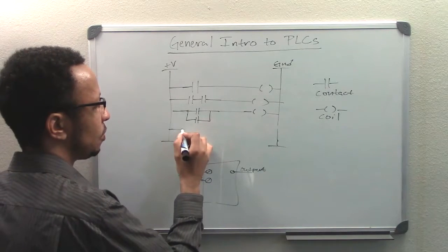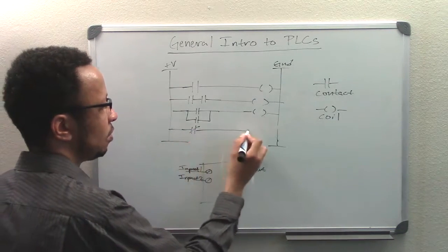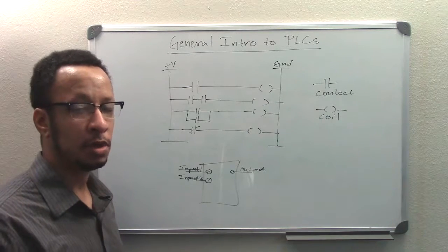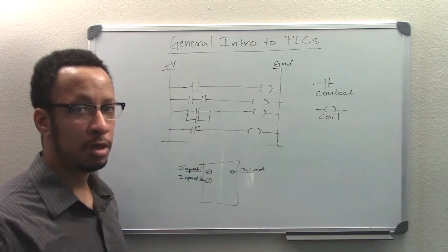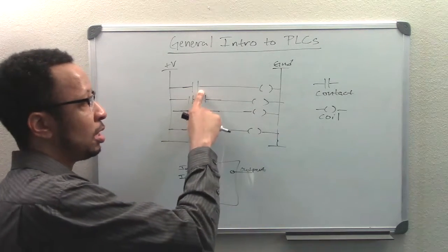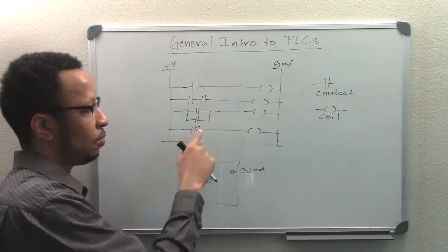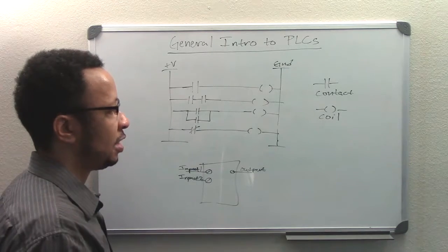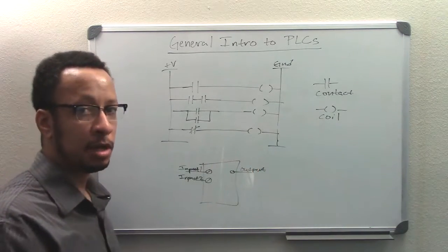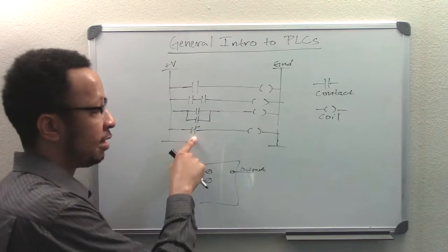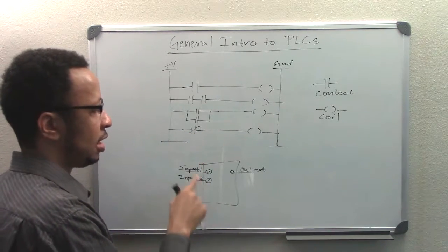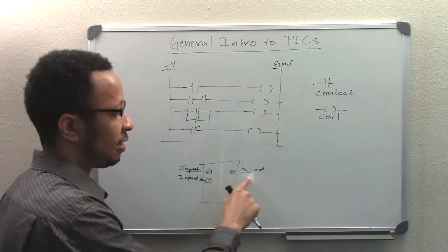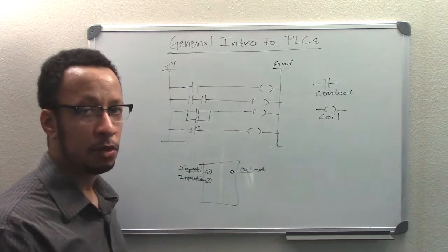And then next and finally, for our NOT function, what we'll do is we'll use a contact that is usually closed. Now, in industry, they usually call that normally closed. So these would be normally open, and this one, with this line drawn through, it means normally closed. If it's normally closed, then it means that this is on without any button being pushed. But if I push a button and I energize the input here that's connected there, then it means that it's going to open it up, and then this is going to be de-energized. And then if this is connected to the output, then it will turn off.